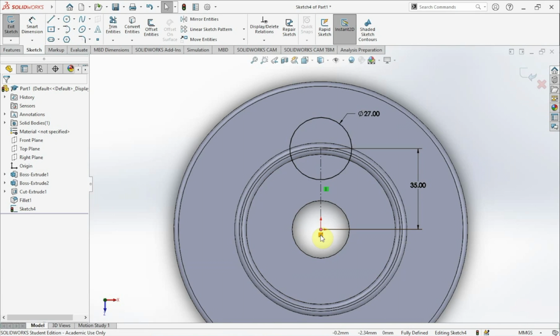It's very important because everything has to lock in place. It has to be coincident, or if you're working with a line and a circle, we have to know if it's tangent. If it's not, then our drawing is not going to be defined. The way you know if your drawing is defined is when all your lines are dark or black. If your lines are blue, then your drawing is underdefined. Or you could just see down here, it's directly telling us that it's fully defined.